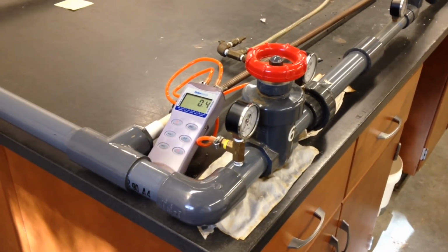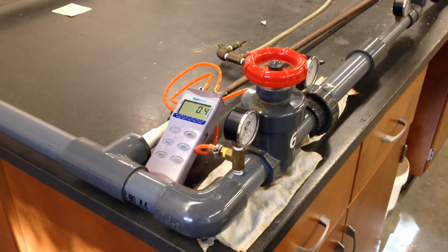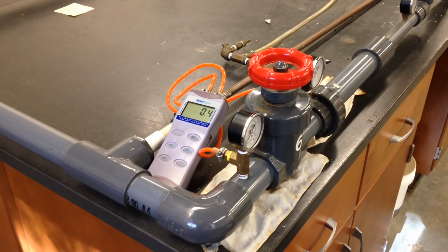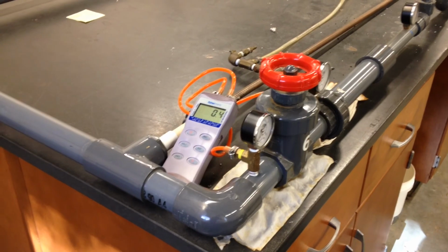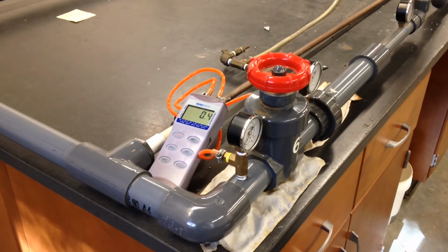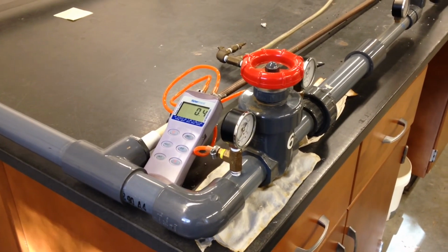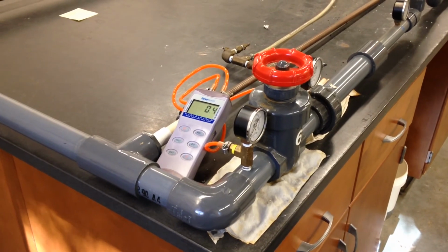Now, the gate valve has 4 settings. The first setting is full open. The 3/4 open setting is 2 turns down of that knob at the top. The second is 4 turns from the top, and that's half. And 6 turns from the top is the 1/4 open setting. Those are not perfect, but they'll give you a range which you can work with, and that's the range you will be seeing in the videos.